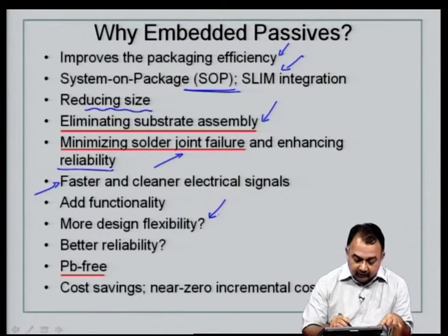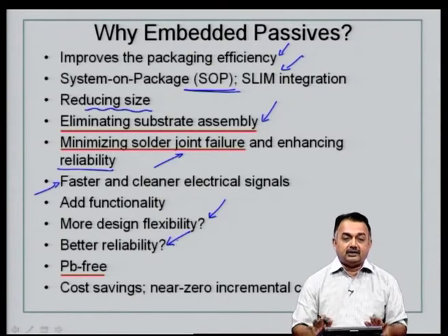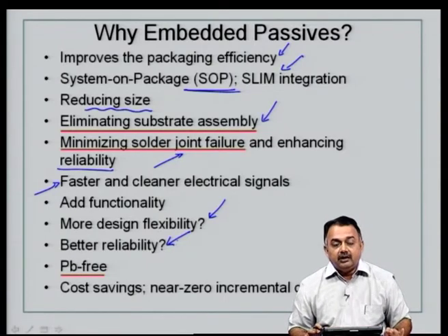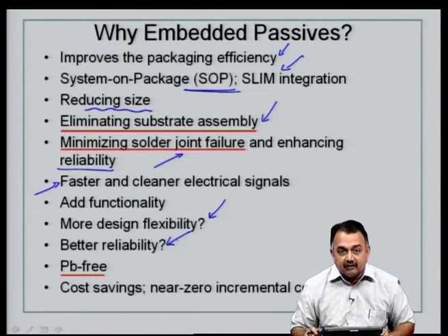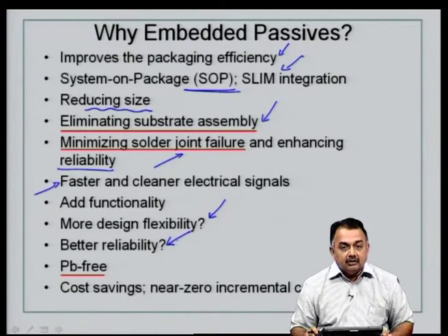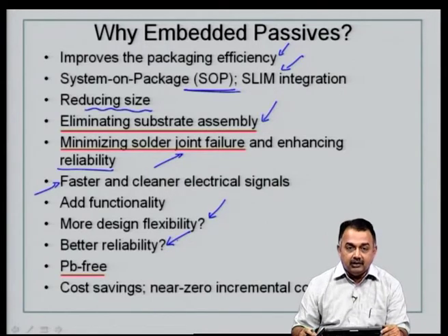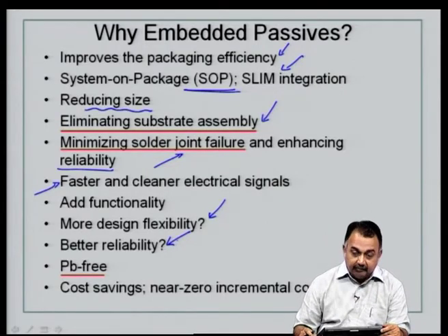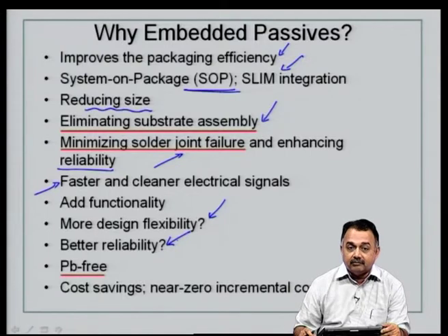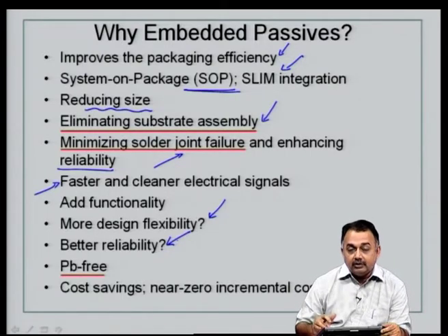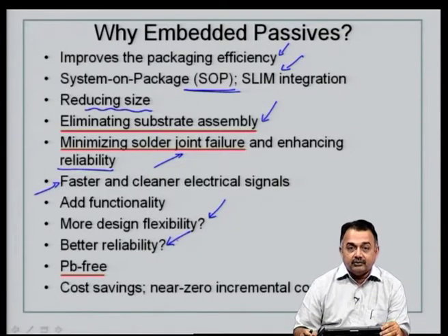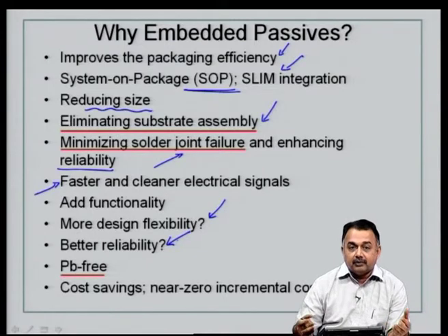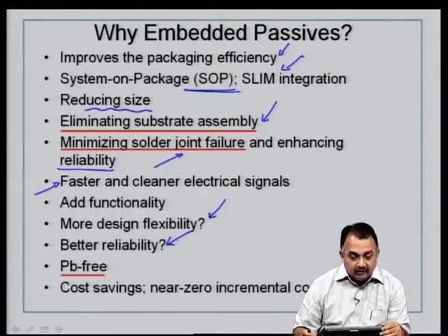Better reliability could be a question, because industry today has really understood well the plated through hole and surface mount device formats, and thousands of products have been built using this format, and people have understood the reliability issues from this format. Now, moving over to a new technique, which is hardly about 5 to 8 years since prototyping has begun, there is always a bigger question mark on how reliable this will be.